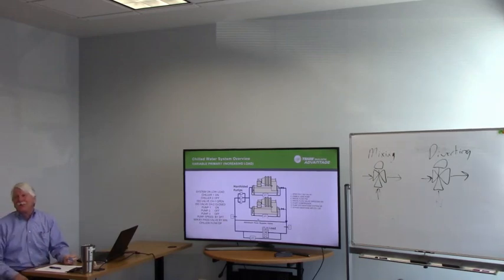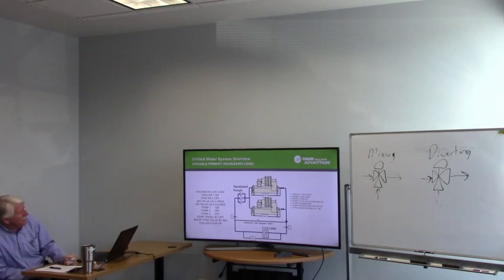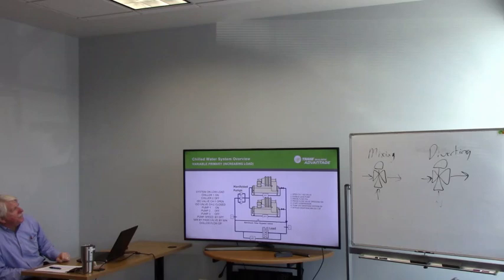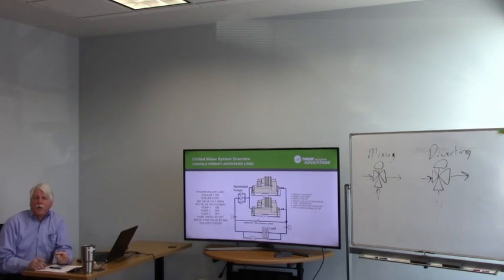We don't have any gear-driven water pumps that I know of. So the idea is you always want to make sure you have a path for the water before you turn on the pump. So you open the valve, you enable the pump, you let the chiller prove its flow. Our standard is we try to put 2 proofs of flow on the evaporators on all our chillers, okay? And what that means is the IFM. Everybody know what an IFM is?